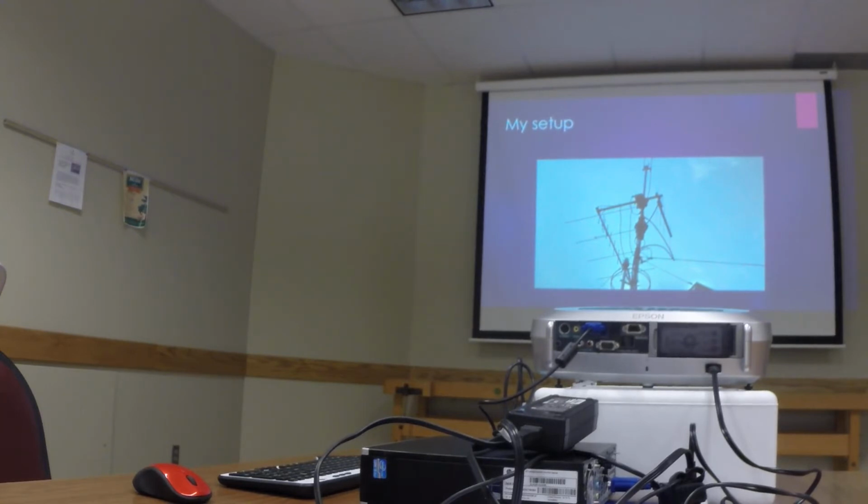That's what I have. Do you have the antennas yet? No, I mean, I have a Yaesu VX-5R. Now again, it's simpler because you don't have the tones and you don't have the frequency shift, so you have to make sure that you have those shut off. A lot of times you're not going to because of the repeaters that you're set up to work. You shut all that off and then work them straight.